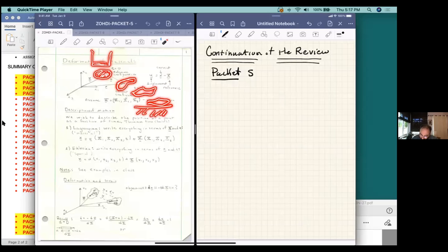So if you really wanted to do a deep analysis that goes beyond just simply treating it as a rigid body, as we did in the very first project, you would really want to go through this whole concept of deformation and strain. And I can assure you it's a rich and beautiful topic, but certainly one that is quite time consuming. If you were to write a 3-dimensional finite element code for a problem like this, you would have to attach a mesh to this kind of an object and then basically track how the mesh deforms as the body is starting to undergo extremely large deformations.